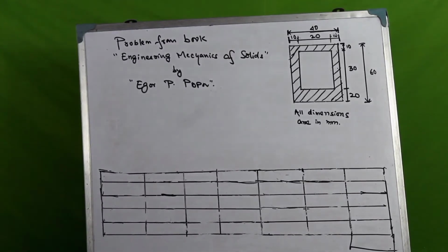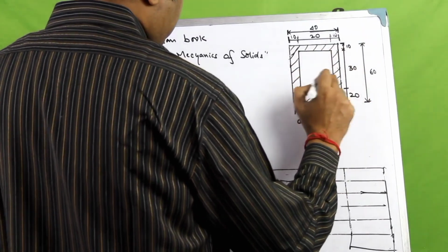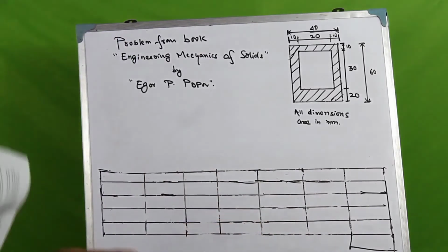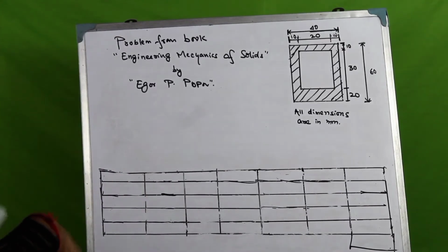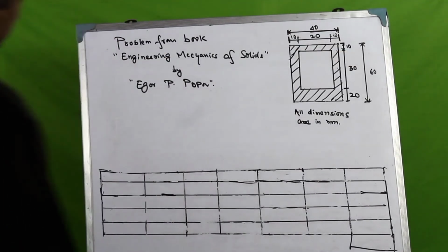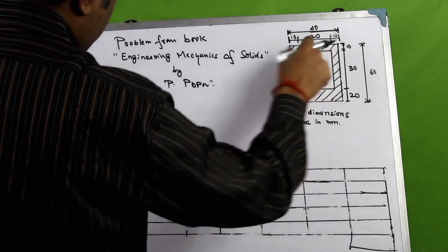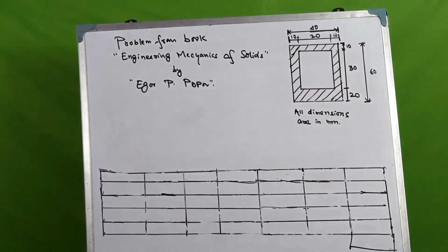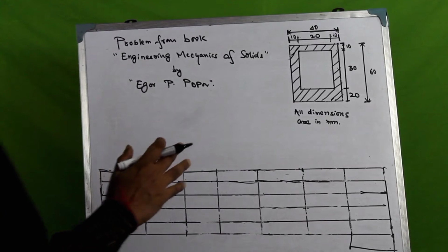Now, one of the things that we definitely can do is take each individual component like we had last time, find the moment of inertia about its individual centroidal axis and transfer it to the overall centroidal axis of the whole cross section using the parallel axis theorem. In that case we had to take 4 components, 1, 2, 3 and 4. But here we will take a far easier approach, and we will consider 2 sections.